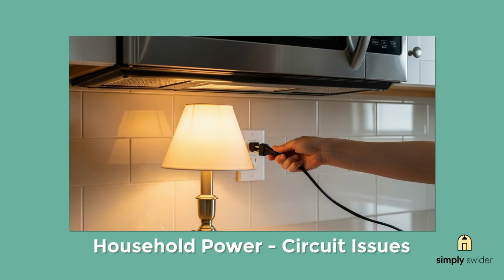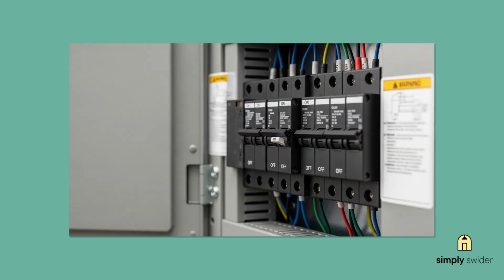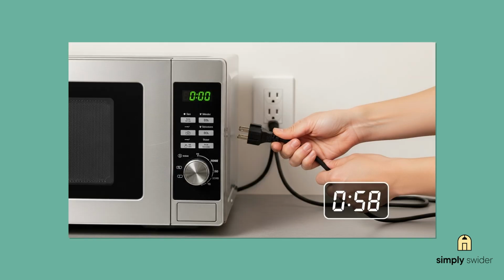If the clear button doesn't work or the PF code returns within 24 hours, you have a power supply issue. Here's your 3-step test. First, plug a lamp into the same outlet. If it doesn't light up, the problem is your household electrical system. Second, check your circuit breaker panel for any switches in the middle position or pointing left. Third, unplug your microwave for exactly 60 seconds, then plug it back in.